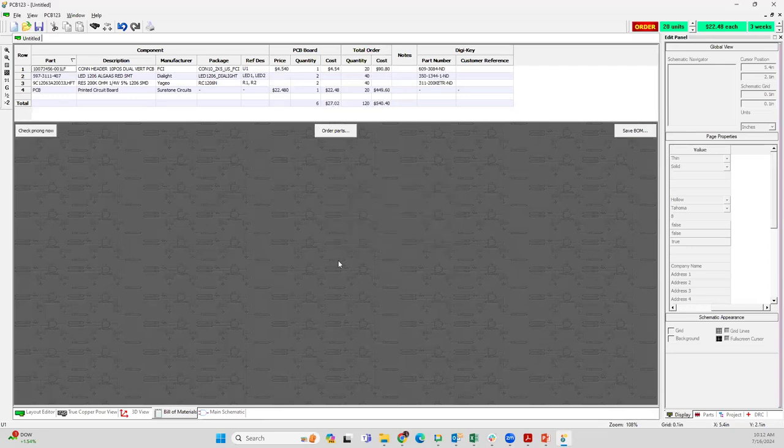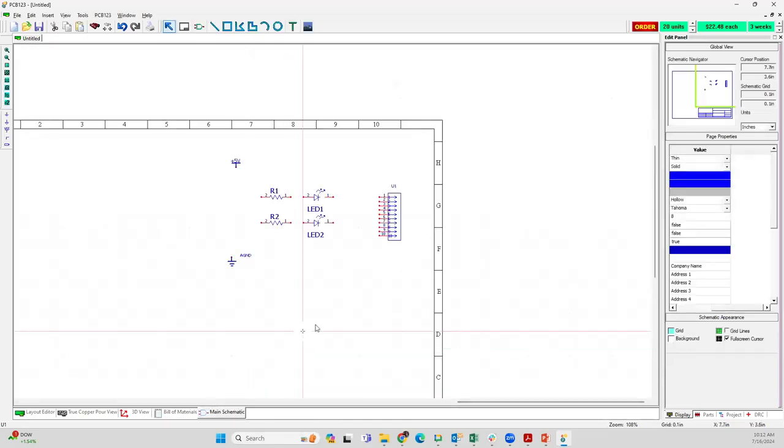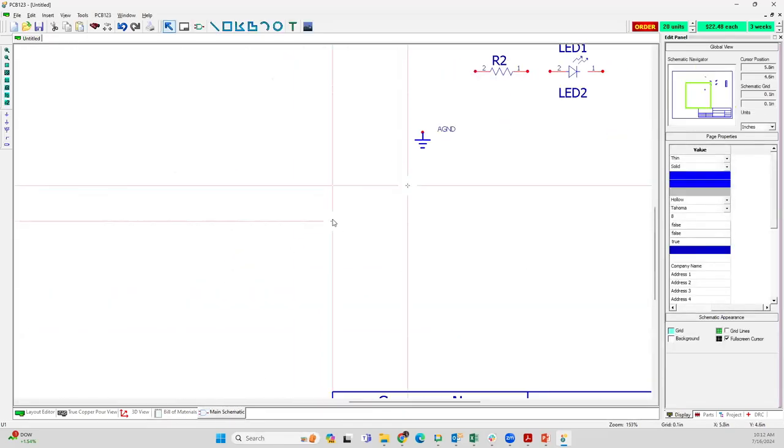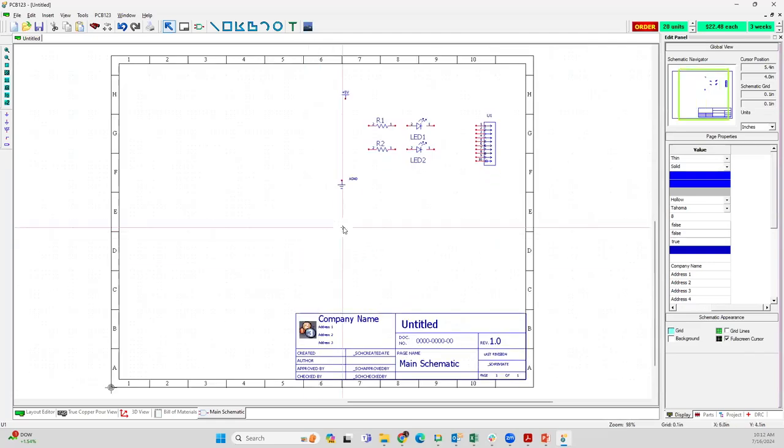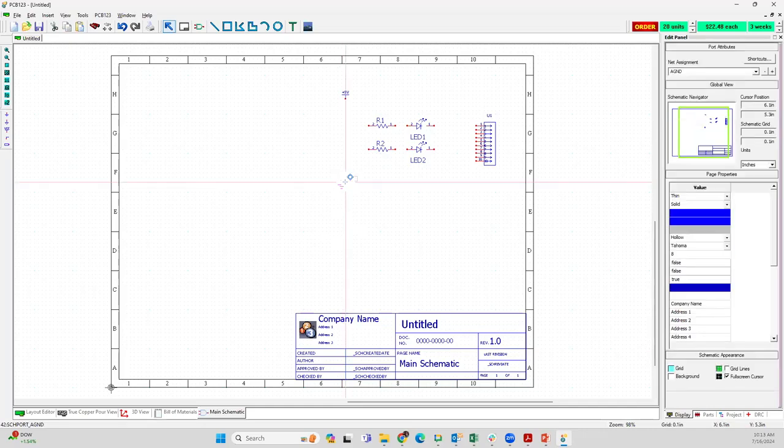And it found some below, it didn't find some of them. That's a nice feature. If you know for a fact that the parts are available at DigiKey right now, then it will give you the parts. So before I just throw parts on a board that I'm working on, I'll go to DigiKey, find the parts, make sure that they're available, make sure that they're not going to be obsolete, and then put them on the board rather than just put a whole bunch of parts and hope I can find them later. That's the best practice, I think.